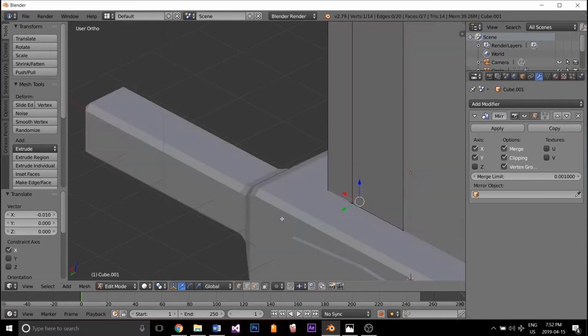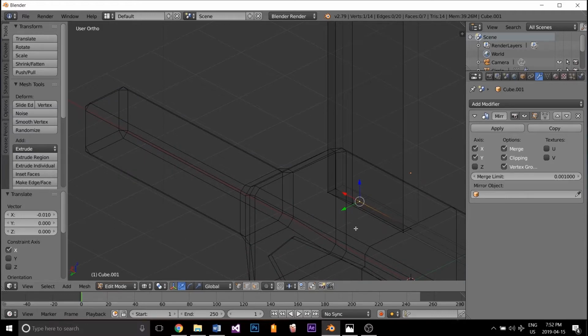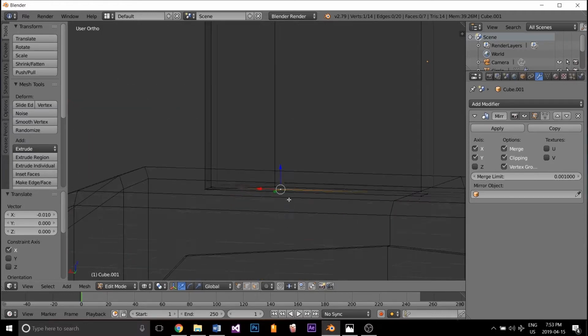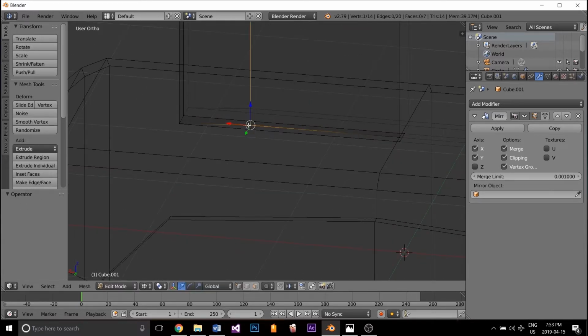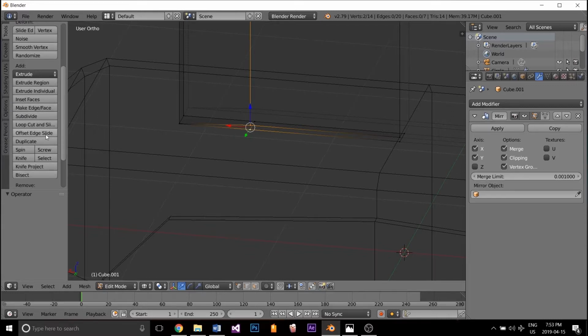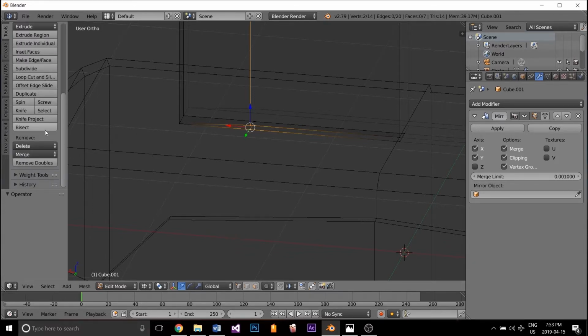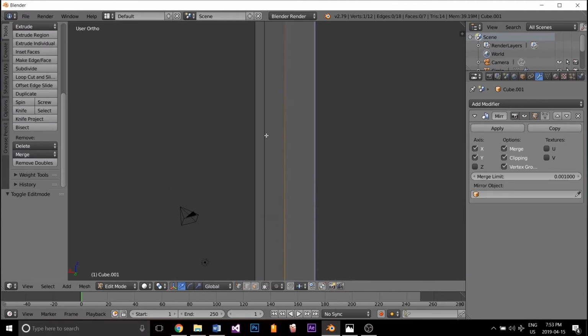But once I'm in, I'll be able to, oh, right. If you click Z, you can go into your wireframe mode or access it from the bottom here. So if we go to our bottom face, which is this guy right here, we can line it up. I already have a face there. So I'm going to grab this vertex and the bottom vertex I need to attach it to, and I'm going to go over to the merge tool, which is in our tools to the left at the very bottom, merge, and I want to merge it at the last vertex I clicked, which was the bottom one. So I'll have to do that on this side as well. Okay, so now this face is on.